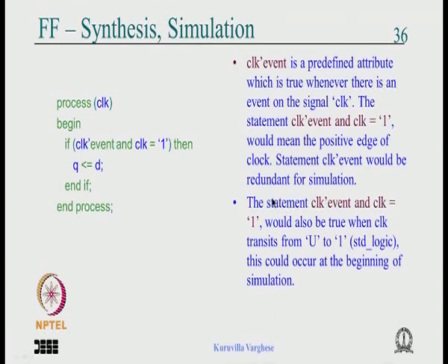There are two things to remember. When you say clock tick event and clock is equal to 1, we are reasoning out the behavior, saying that it means the positive edge. Now if you hunt around the syntax of VHDL and come up with some other ways of describing this particular condition, it may not work with the synthesis tool, because this is accepted as a template for the positive edge.